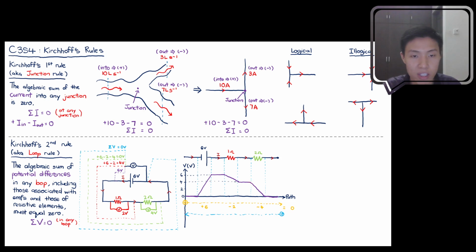So that means that if I choose to walk through this loop in the opposite direction, what I'm seeing is the opposite of what I understand. If I follow the direction of current, I know that when the charge passes through the resistor, it should give out energy to the resistor. That's why you will lose energy. But today, if I walk through this path in the direction opposite the current, when I pass through the resistor, instead of a loss, I'll be seeing the opposite of loss, which is a gain.